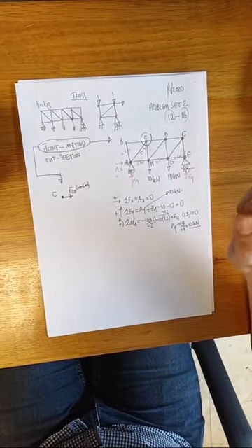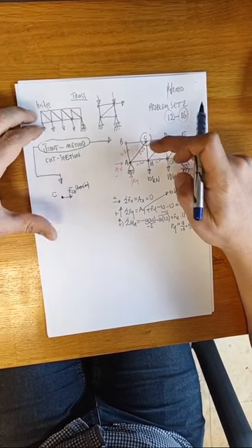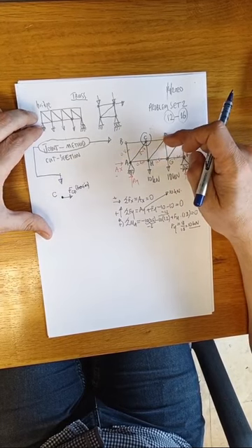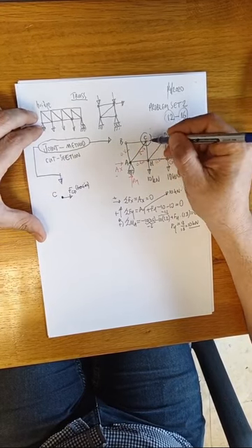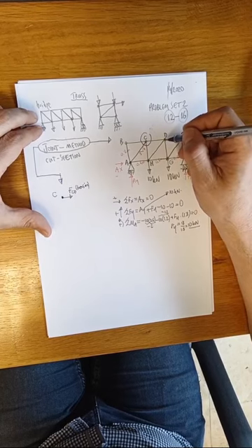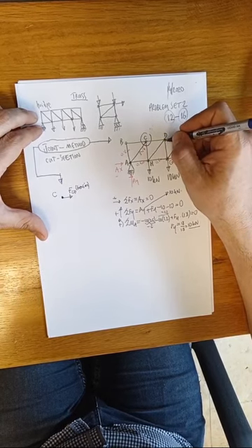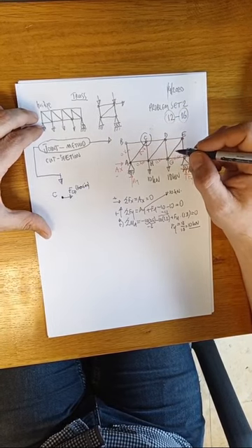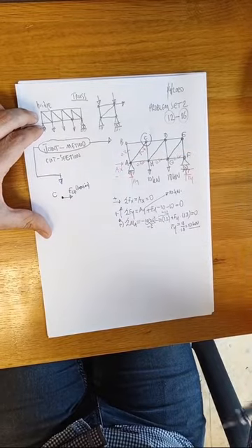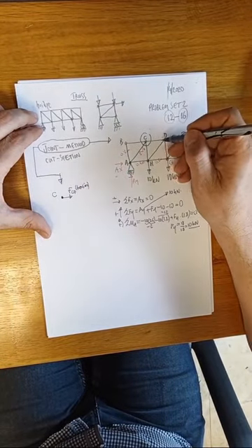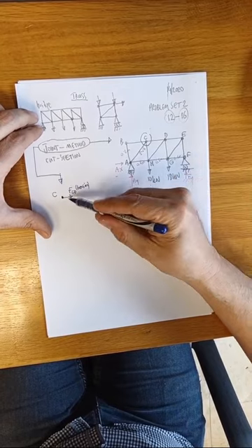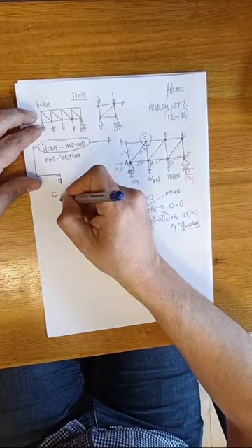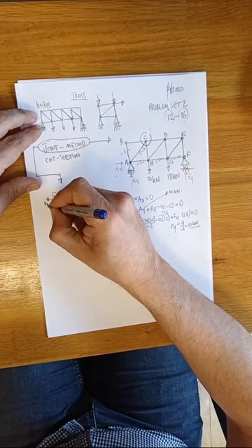If CD is in tension, what does it mean? It is trying to pull point C. Consider yourself between C and D. You are holding point C in hand, and your feet are on point D. Between this and there you are tensioned. What happens? You are pulling point C toward yourself. I'm taking the CD member internal force as tension FCD on the right hand side, as you see. In the other direction, FBC, I'm taking FBC also in tension like this.